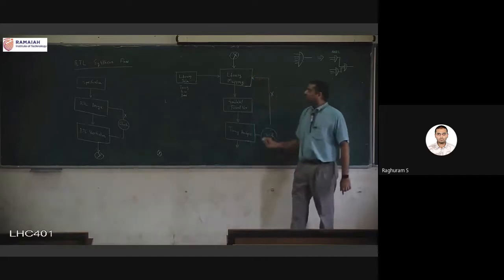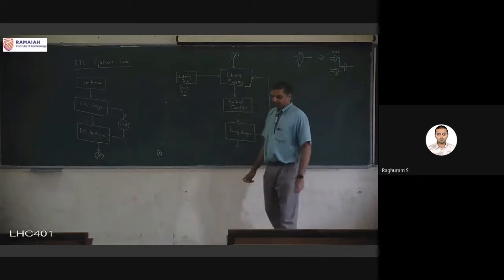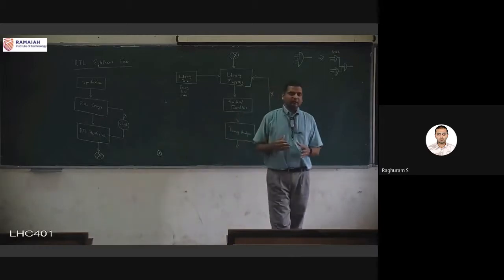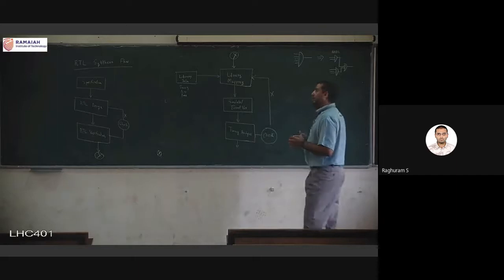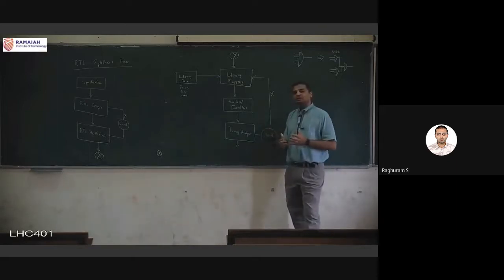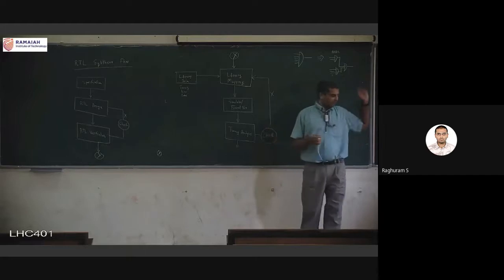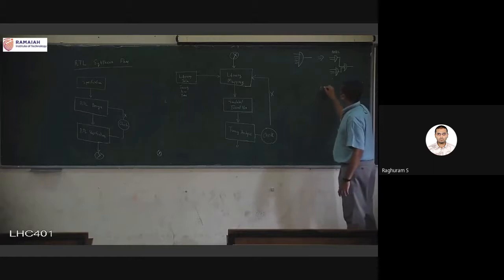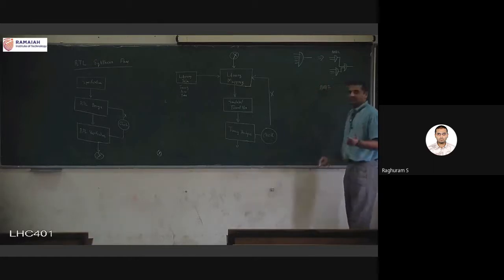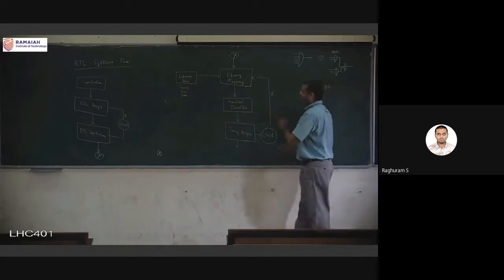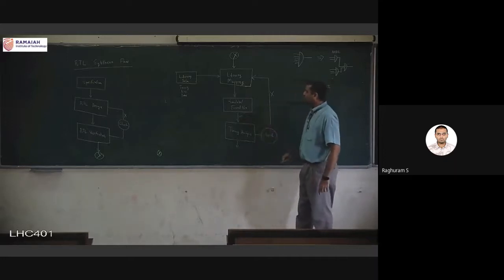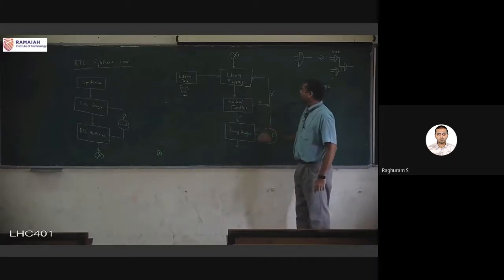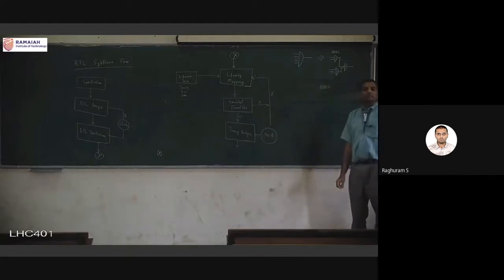What is the meaning of go back? This is the way where we are trying to maybe change the mapping. Take this example itself: AND 2 is one cell that is there in the library. We have used this in our mapping, and unfortunately the simulator is okay, formal verification also okay, but the timing analysis is giving me a problem.